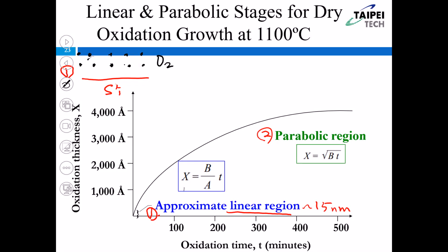So the oxygen atom can react with silicon directly, okay? Directly. So this is the first stage, within the oxide thickness of 15 nanometers. So we say it's a linear region. It means the oxide thickness is a linear function of the oxidation time.